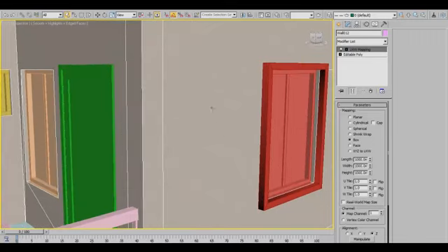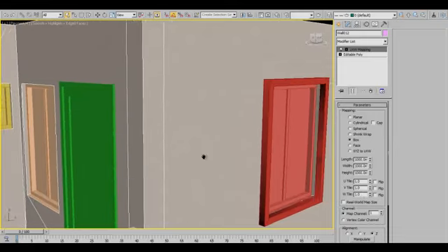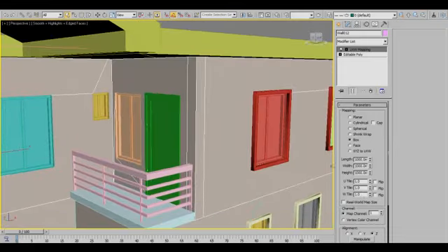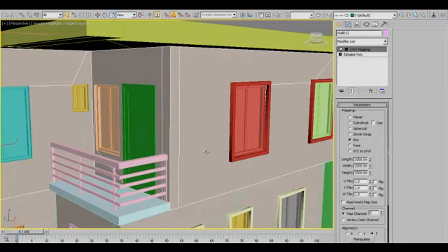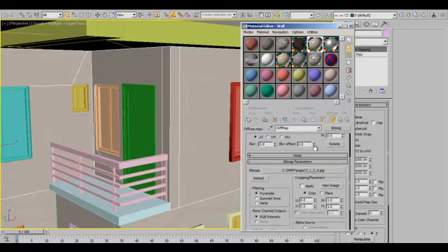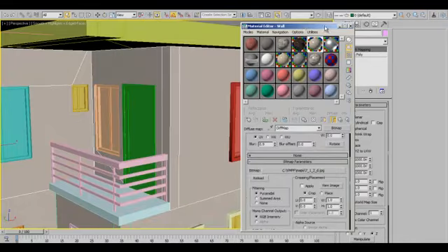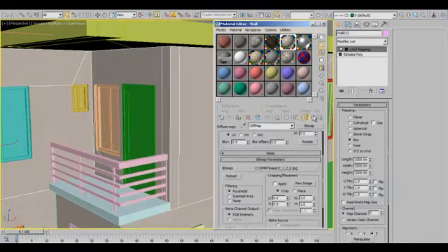If you want to adjust the scaling, I always advise you do it right here and change these units to adjust the scaling. There are other ways you could do it, but that's the way I do it anyway. The reason why I'm using 1000, 1000, 1000 for length, width and height is because my material, particularly the base material, which is a standard for all of them, is a square material, not rectangular, so it's easier for me to just apply 1000 to length, width and height.